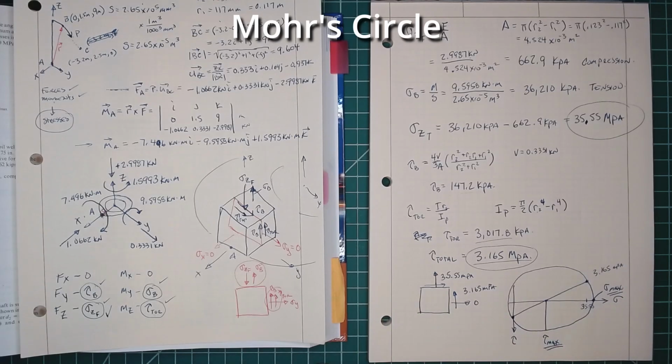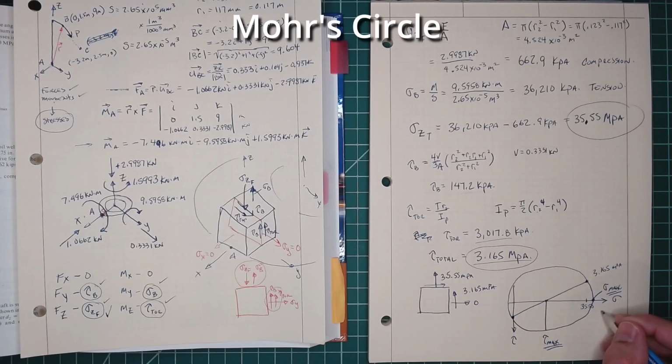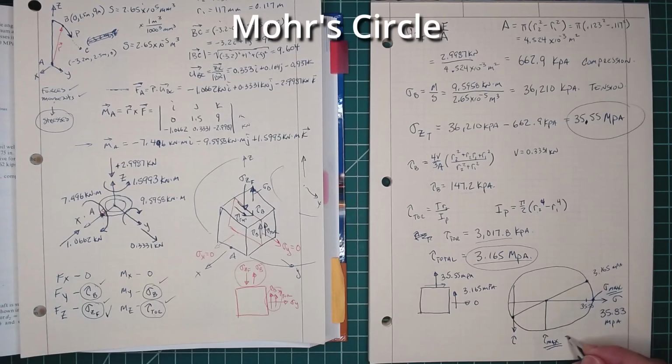In this case, you can go through and plug that all in, and it's going to turn out that our sigma max is equal to 5.83 megapascals, and then our shear tau max is going to be equal to 18.05 megapascals. So that's going to be the solution to part A of problem 8.5-14. Hopefully that helps. If you have any questions, please let me know.